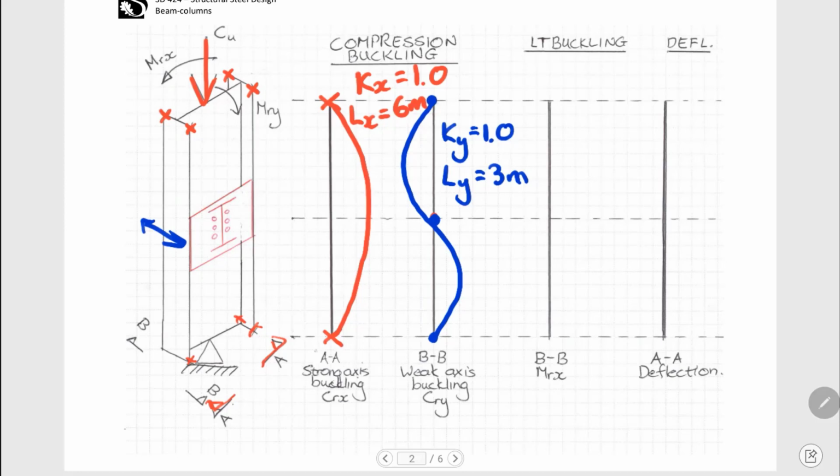Now we come to lateral torsional buckling, and just remember, lateral torsional buckling is failure of the compression flange. Very important: is the compression flange able to move? So now, when we apply a load to the section, here is our moment, and it's going to, for instance, put this flange into compression all the way from top to bottom. And now let's see, where can that buckle out? Well, actually, sorry, I must change that a little bit. The bending moment diagram does swap sides, so it swaps from compression from one side to another.